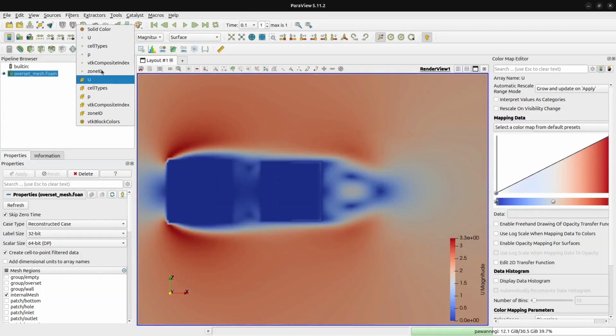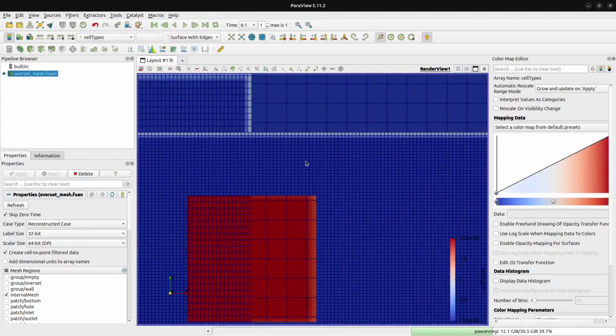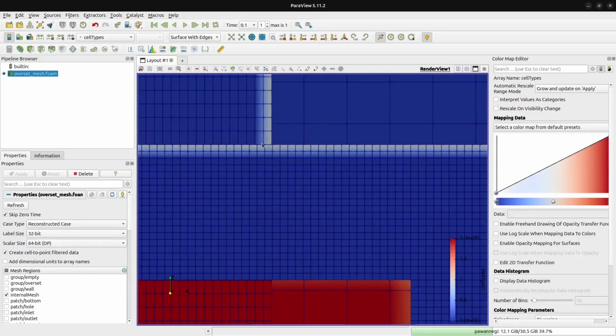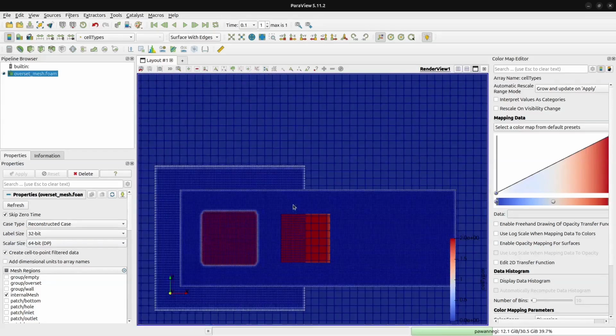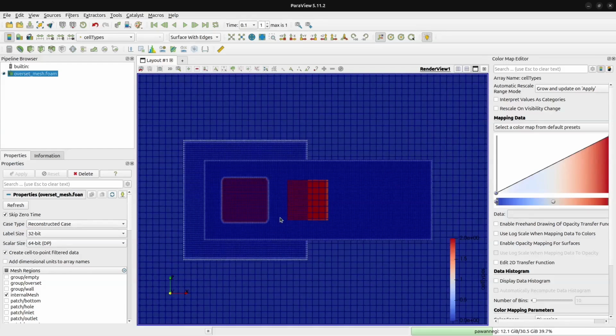And here you can again see the cell types, and you can visualize which cells are interpolating. There is this little bit of overlap, so there we have some errors. Except this, there won't be any error because the interpolation points are different for different domains. So this is how you can have overlapping overset meshes, but this is not the best way to use overset mesh. You should always make sure that overset meshes are completely detached. They should rarely overlap, and then you can expect some accuracy. But you can actually code and handle these special cases and then work with your particular setup.